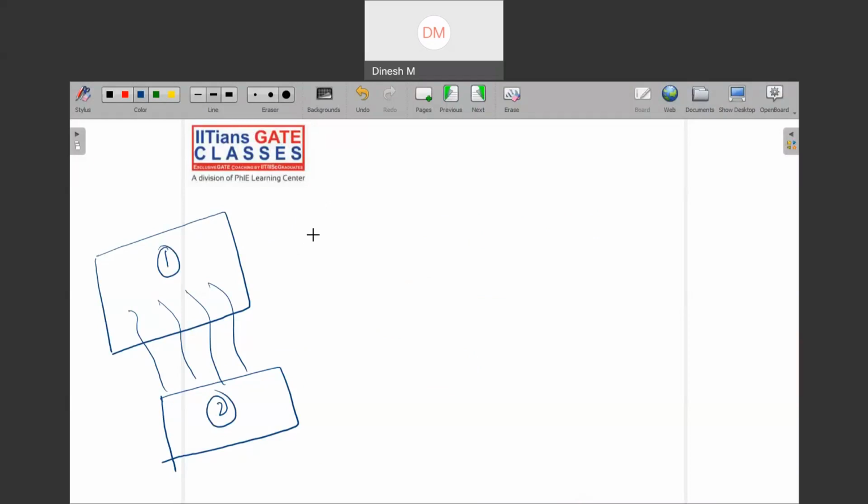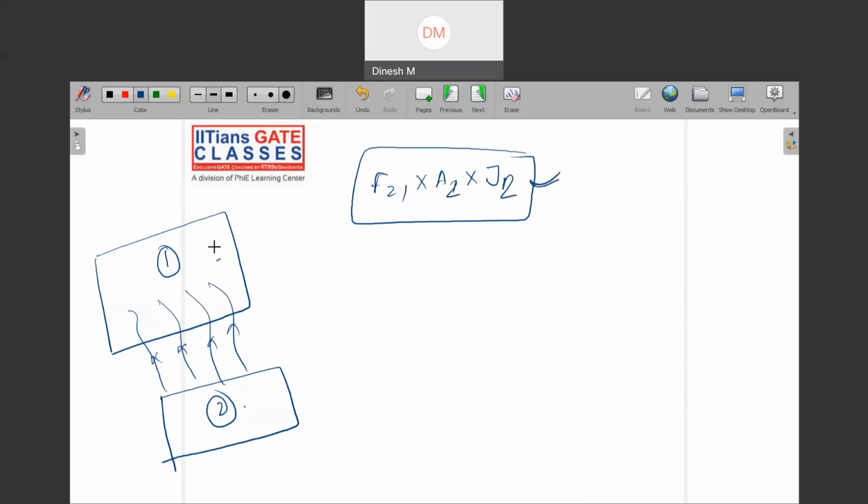Then what you would do is that from this one you have energy leaving this one and reaching this one, then what was that fraction? F21 I know, and the area I know, that what is the leaving one? This one A1, and then if I multiply by whom? J1, then I know that this is the F21 into, not this, this is leaving surface 2, no? So A2 and J2. So this is the amount of heat exchange from 2 to 1. Got the idea?